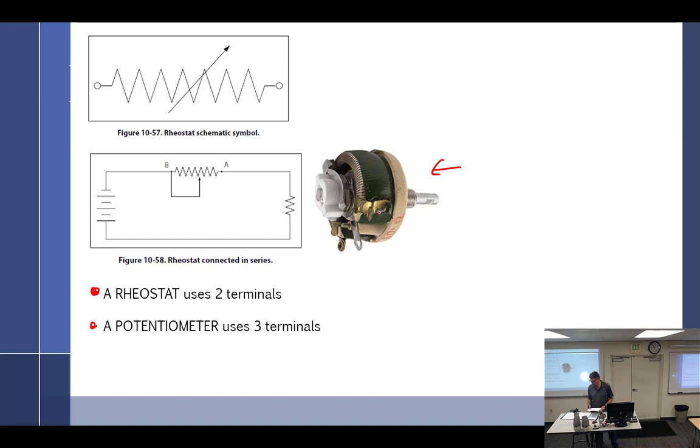So how does a rheostat vary its resistance? Physically, how does it do it? I think schematically, it would make more sense to be like this with 2 pins. And this one is not pinned to anything. Yeah. So that way is less resistance, because if we got to right here, there'd be no resistance, right? And this way is more resistance because we have more of the resistor. A scaling. Yeah, scaling. And so that's how I would look at it.